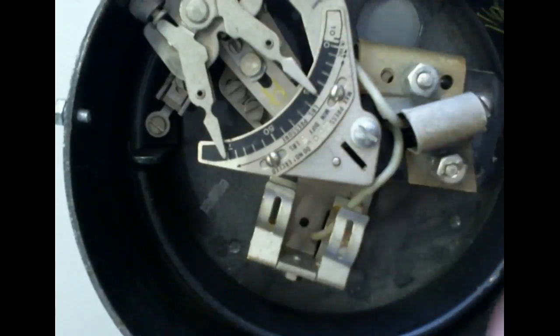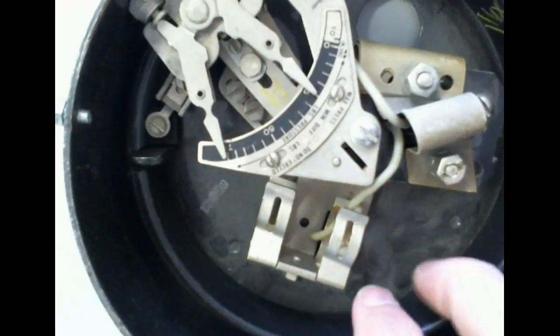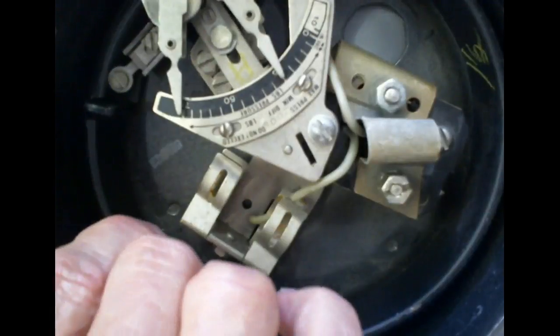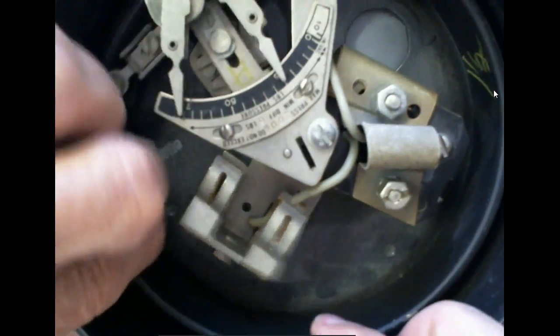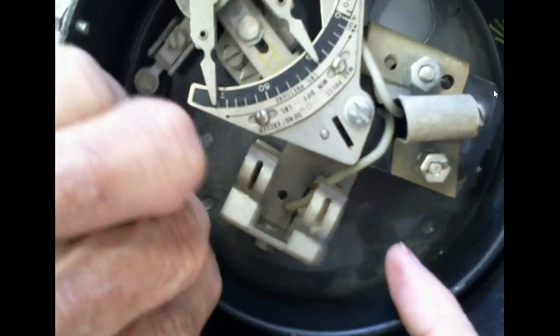Right? You understand that? So we could put a digital sensing element on this. Normally, pressure sensors, we combine it with something else. That makes sense? So this right here means nothing unless I combine it with something else. So I could make this move a wiper on a dial that indicates pressure, or I could put something in here, and then I can set a place where it trips, right?